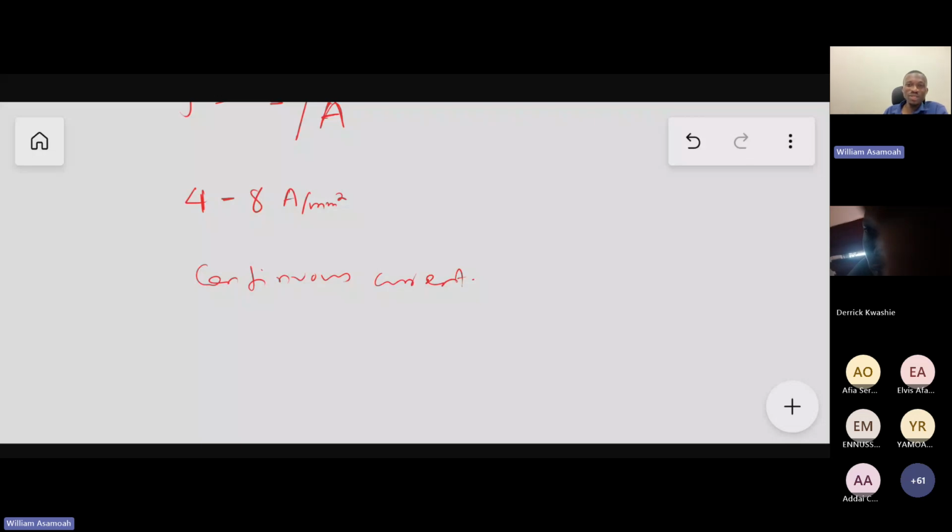So we don't use inrush current because inrush current happens over milliseconds. And when it happens, it doesn't happen again unless you are turning it off and temperature is coming down. As long as the device is operating, it doesn't happen. That's also one of the reasons why when you go to the industries, they don't usually stop their large industrial machines, unless there is mandatory maintenance.